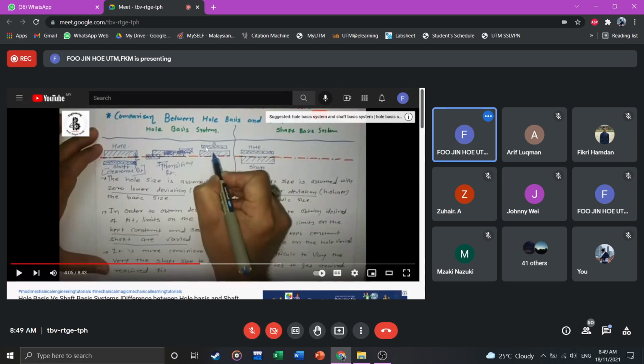The shaft is always bigger than the hole because it's on top, or if it's at the bottom, it means the shaft is always smaller. If it's intermediary, meaning some on top, some in the middle, just like this middle figure here, this is a transition. Sometimes bigger, sometimes smaller, sometimes loose, sometimes tight.